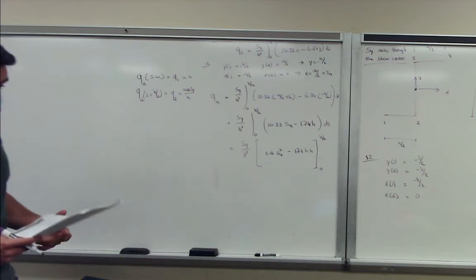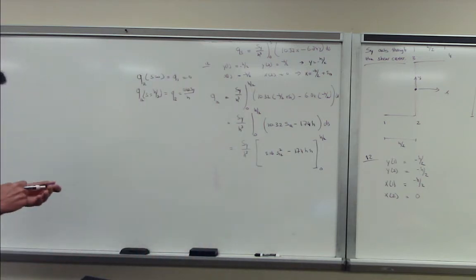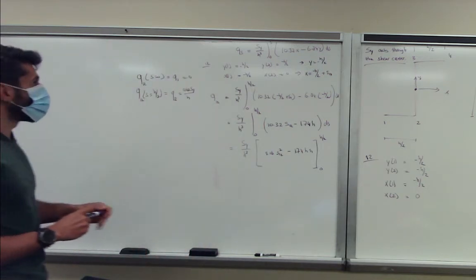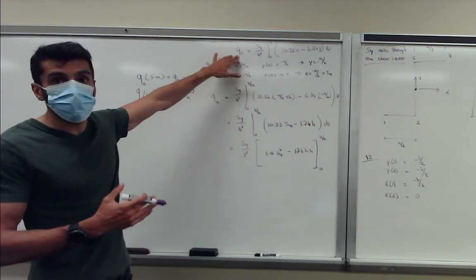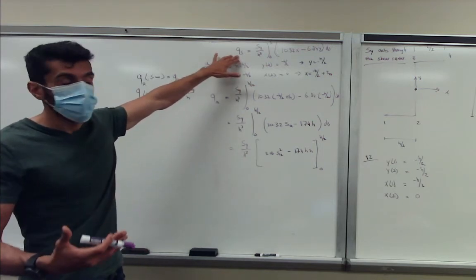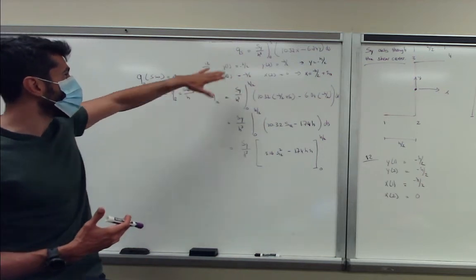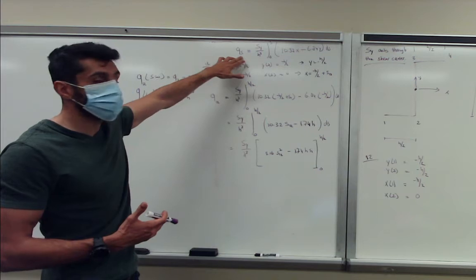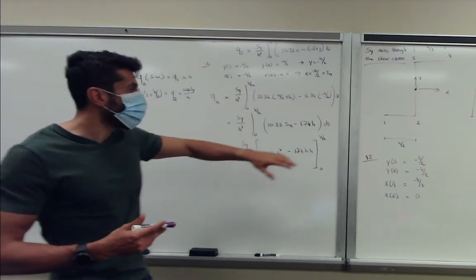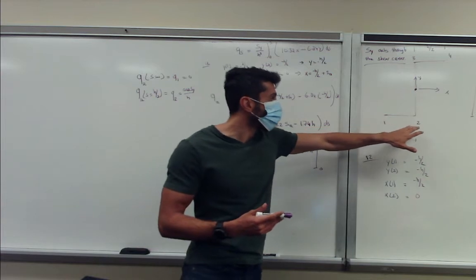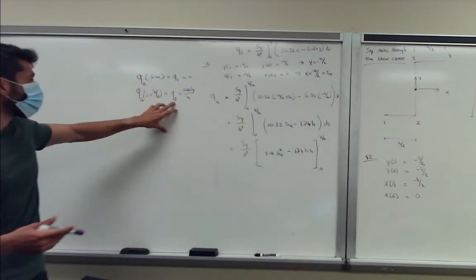So there are a couple of things that we have to be careful with, and there can be confusion in the beginning. So this equation, q of s, gives us the shear flow along that path s. We indicate the different paths we take by shear flow q and then two subscripts: 1, 2, 2, 3, 3, 4. And then we can evaluate the shear flows at those locations, so then we use a single subscript.